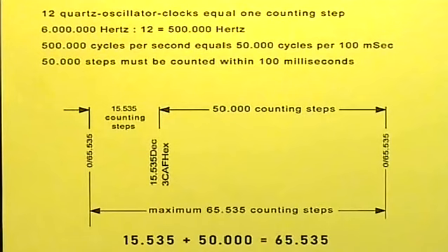In the interrupt sequence that follows, the timer T0 counter must then be reloaded in such a way that a new interrupt occurs after every further 100 milliseconds. The process then continues.